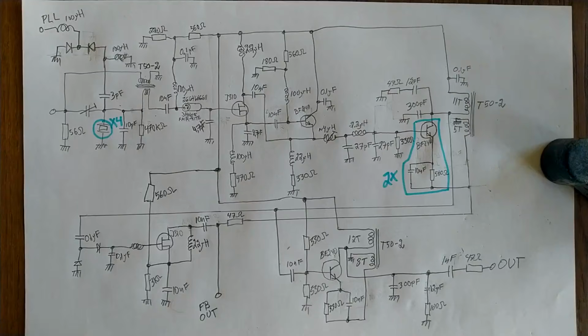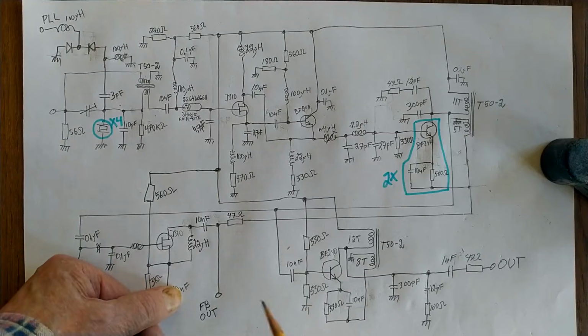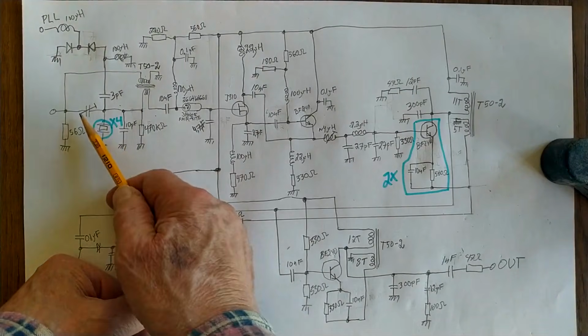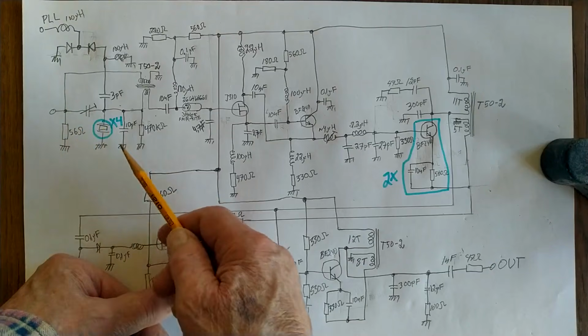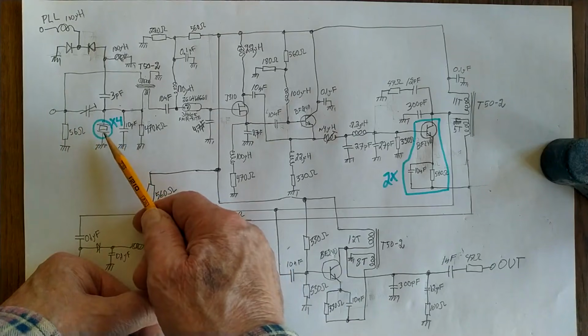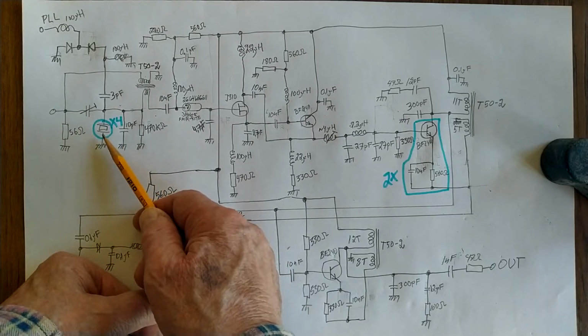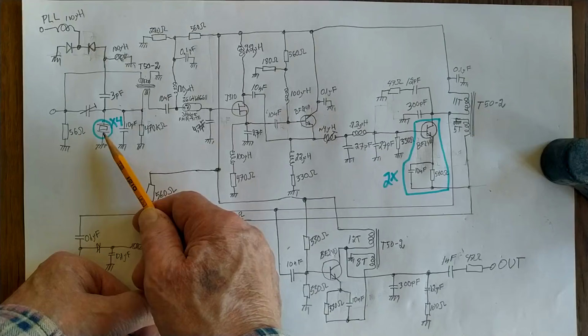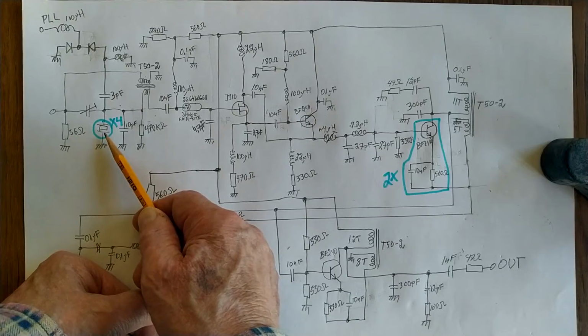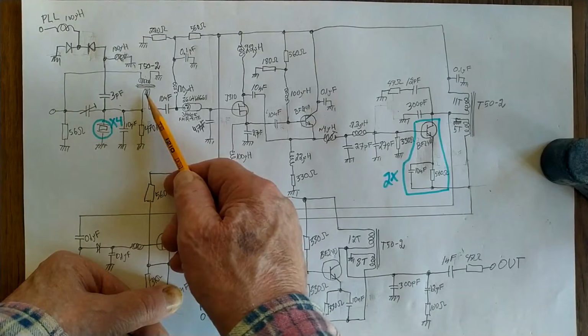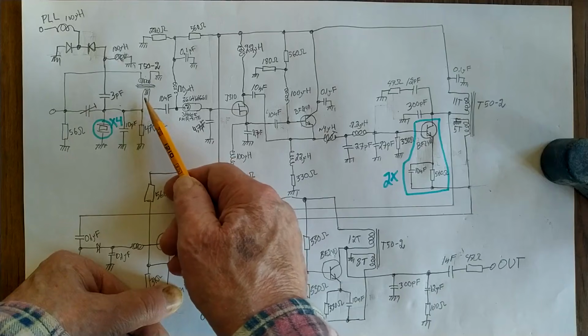Here is the circuit diagram of the oscillator. The way to tune it is first to set this capacitor for the Q of the crystal to degrade just a little from 1.1 million down to 1.07 million or something like that. Then this transformer is to get a good stop band attenuation.